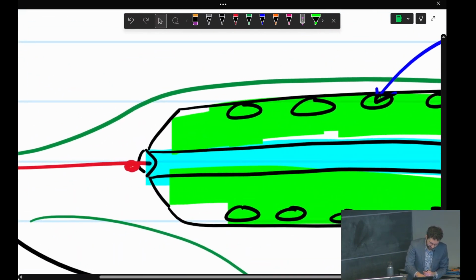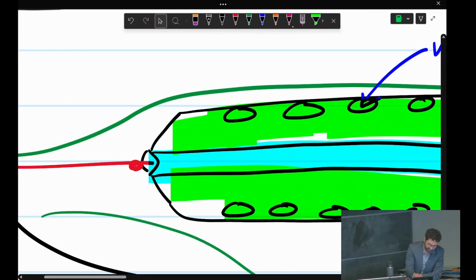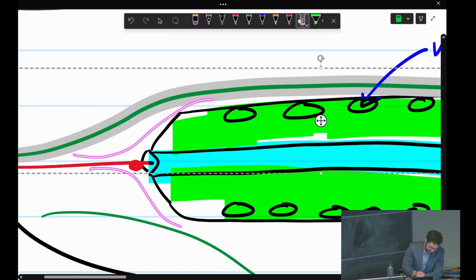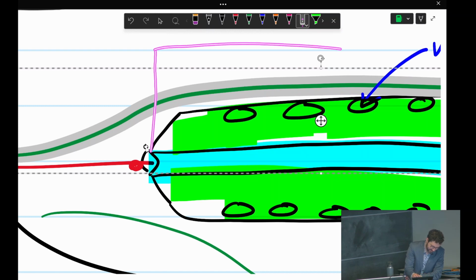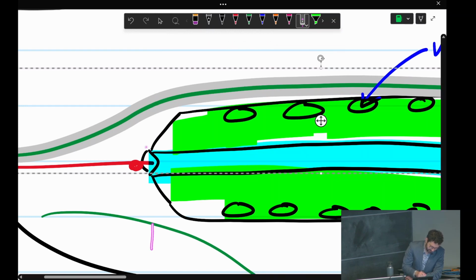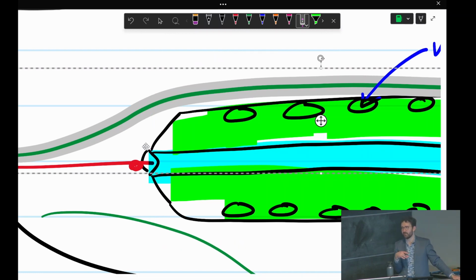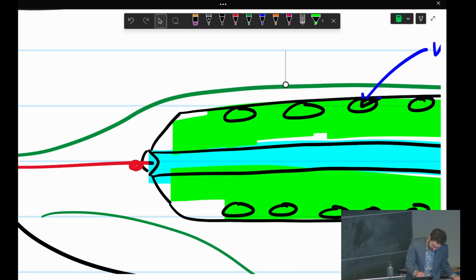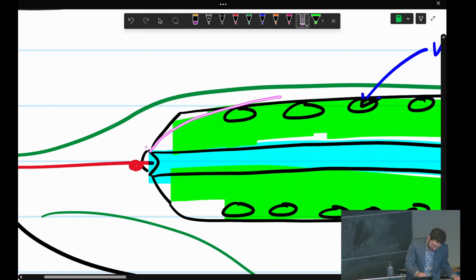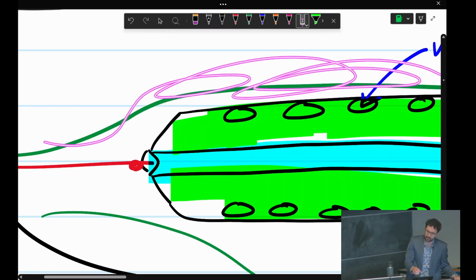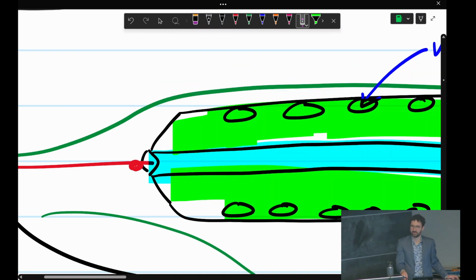The main issue is that this isn't a single point, right? If your flow is coming in like this, and say you design your pitot probe so that it's like a flat plate, it's an additional source of drag, and then also your static probes here won't give you a reliable reading anymore. Normally what's done is, this is very smooth, because if you have a flat thing here, the flow will come and mix and you won't get a reliable static pressure reading out there.